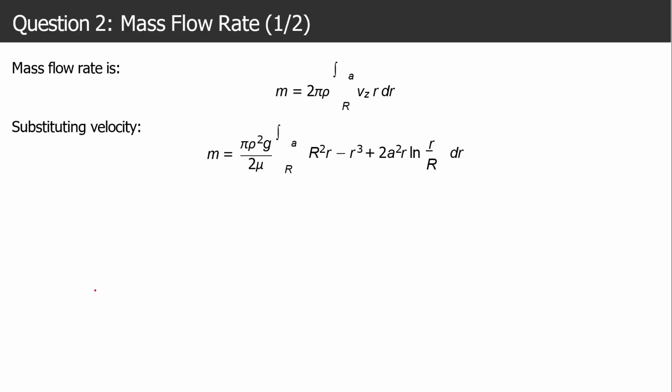And for mass flow rate, we have vz, the velocity, into 2 pi r. It's nothing but area into density into velocity. As we can see from a unit balance, it will be mass only: kg per meter cube is rho, and this is meter cube per second, so we obtain kg per second. This is how we get the mass flow rate. So integrate vz r dr from r to a, where a is r plus delta, throughout the liquid film. So we'll obtain our mass flow rate.